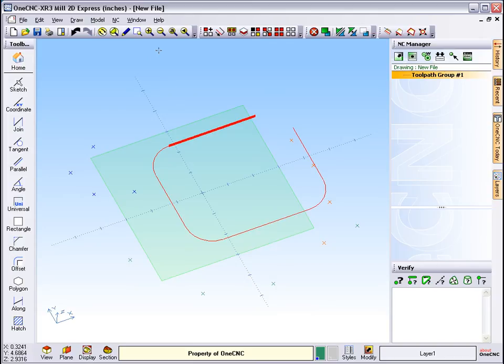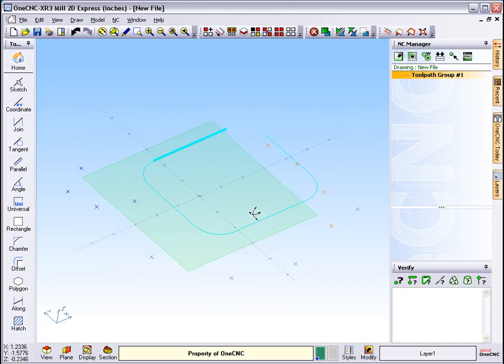Now this video is getting a little bit long, so I need to finish. I think I'll just stop with discussing a little bit about these two buttons down here. These are your color swatches down here. This allows you to change the color of your geometry as you're creating geometry. And let me explain a little deeper. Right now you can see this color swatch is set to green. This left color swatch has to do with all wireframe geometry. Okay? This right color swatch has to do with solids and surfaces. In our case, we're just working with wireframe geometry.